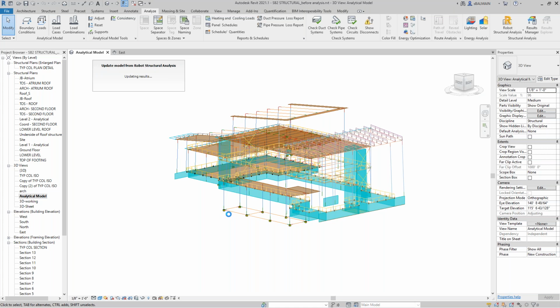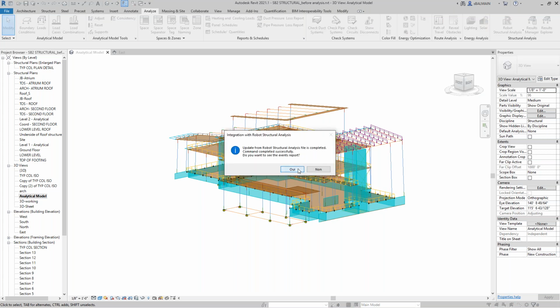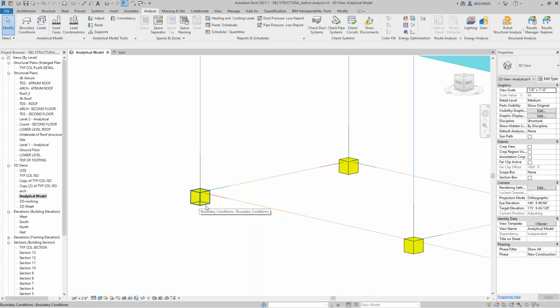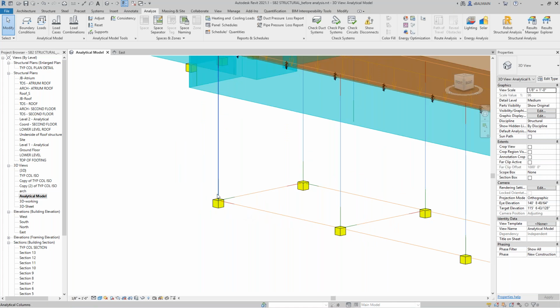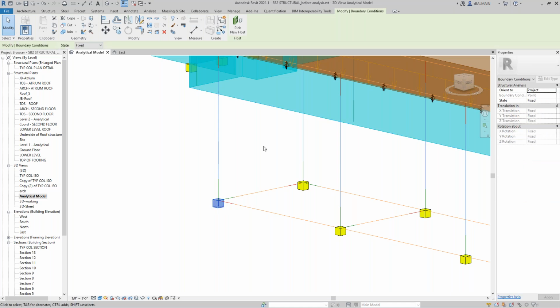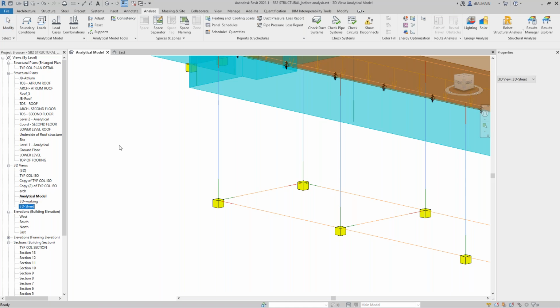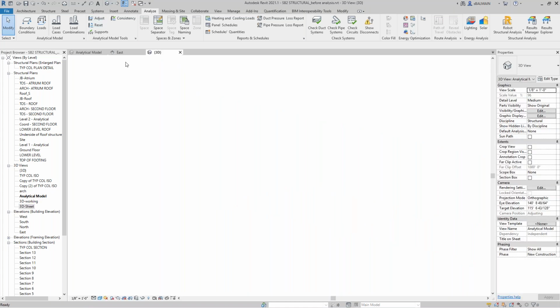So usually I uncheck this and I put here my boundary condition, a support, which is by definition at the bottom of the column, because I see some customer files, or even when I do files, and sometimes I adjust. Usually, if I don't use this boundary condition, I activate the support of the slab, because here, if I look in 3D, of course, there is a support because there is